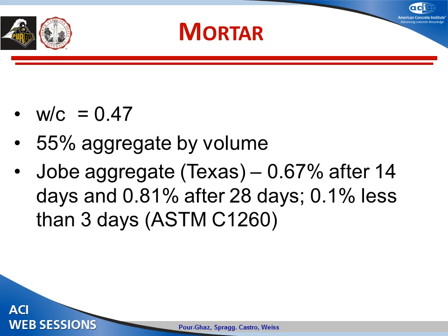The mortar sample we are using has a water cement ratio of 0.47, aggregate volume content is 55%, and the aggregate is a Jobe aggregate that Noel talked about. This aggregate is highly reactive, tested by multiple laboratories across the country. After only 3 days, it passes 0.1% expansion.